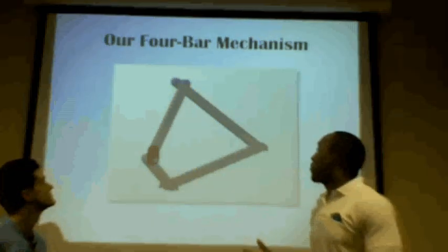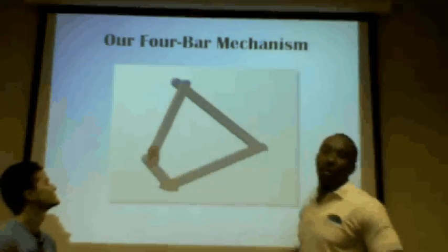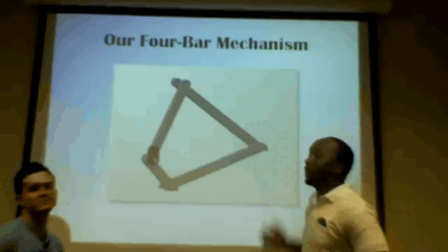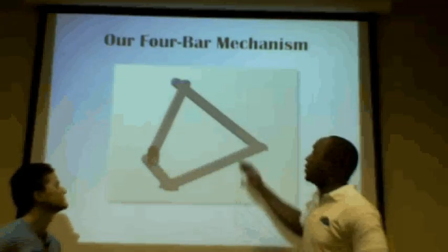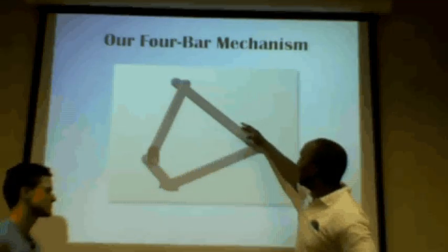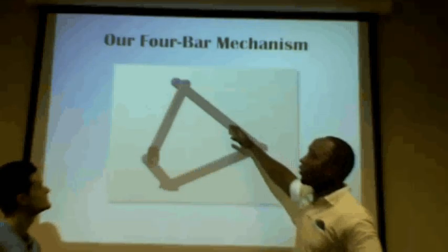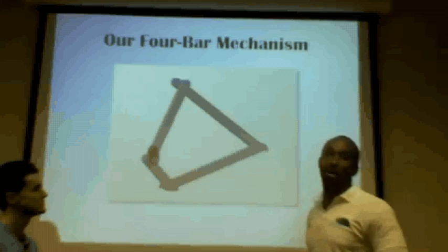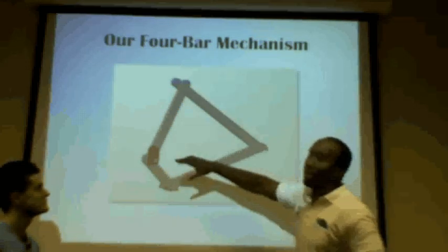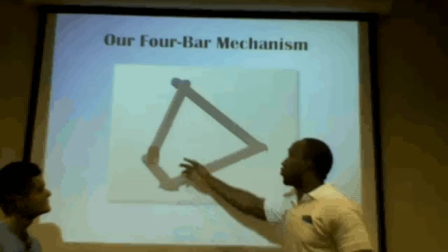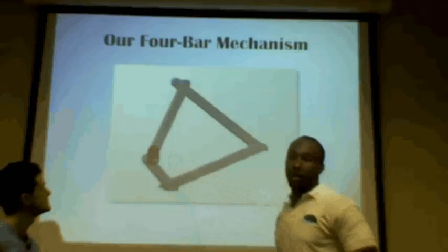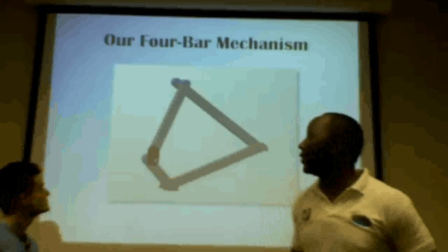Okay, so as previously stated, the 4th link here was our input link. And after calculations, we saw that the link only traveled through an angular displacement of 170 degrees to about 218, which therefore explains why the system rocked back and forth. This trajectory of the extension link is shown in the next slide.